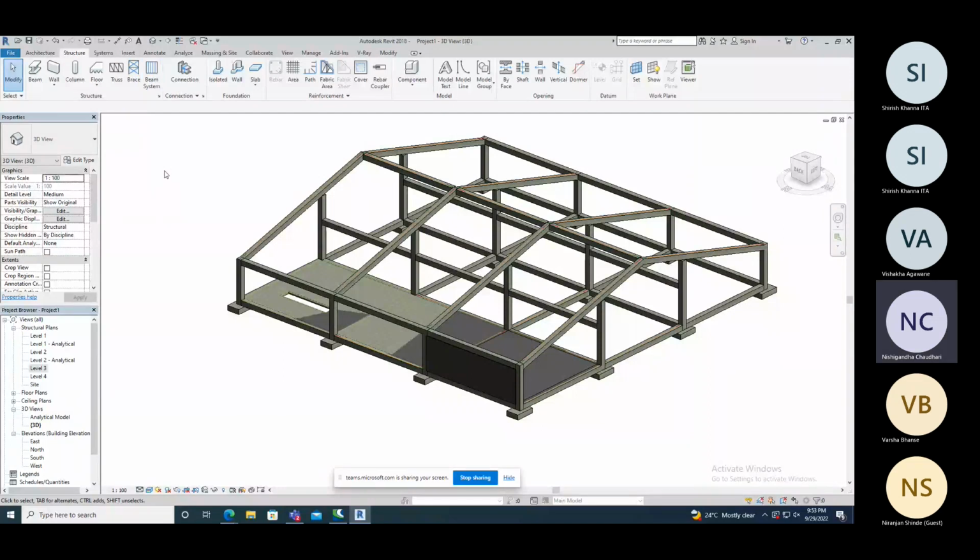Shirish, that's all. One question only. It is related to the model only. If we have just made one beam and copied it, then as an analytical model, the start point and end point have been taken by default. But if I am modeling it one by one, what will be my start point? Will the left always be the start point, or how is it? Because I have to follow the same sequence. Otherwise, my start point and end point will be different, right? As an analytical model, how do you think it works?